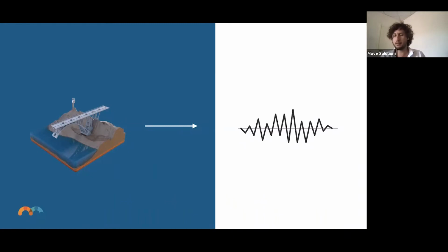So if we speak about the structural market, the structural problem on bridges or other structures, it's not that different if you think about it. We could use vibrations that bring information on how the structure is made, for example, or how long a span is, right? Because, for example, frequency depends on length. So if you get a beam and you get a longer beam, you will have a lower frequency probably. Okay, that depends on mass, on stiffness, on other parameters. But the idea is this, right?